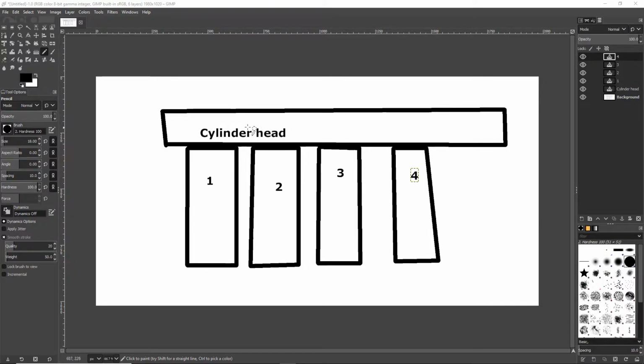Now, if this was a 2-liter 4-cylinder and we filled each cylinder up, when we poured this fluid into the measuring cup, it would measure 2 liters. That's where these numbers come from. The displacement is from bottom dead center, the entire cylinder, times however many cylinders we have.